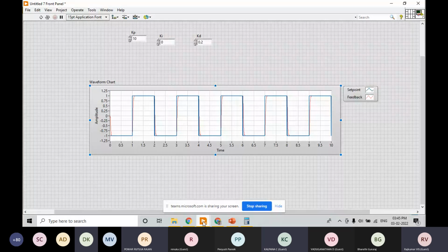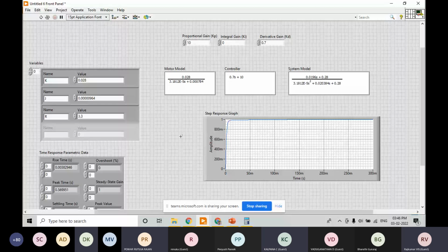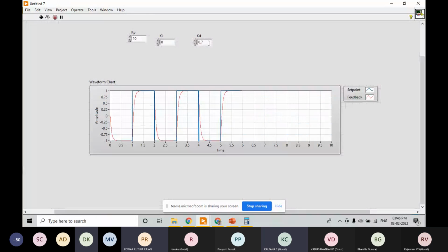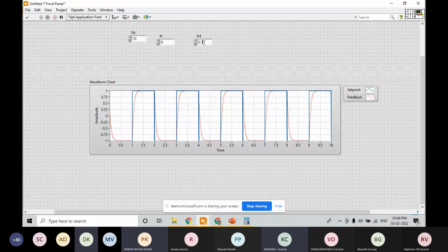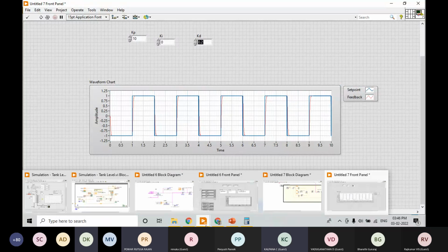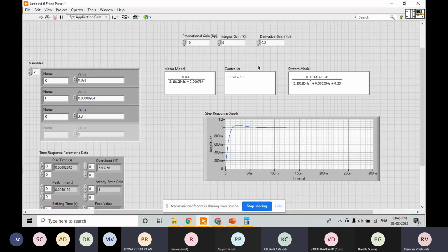So during the simulation, I believe we set some certain values, which I'm pretty sure not all of them applied properly. Okay, it says 0.7. Here we use 0.2, and when we apply 0.7, you could see that it has a very large settling time. Let's try applying 0.2 here and check how it responds. It has an overshoot. Okay, so trial and error will always be there.